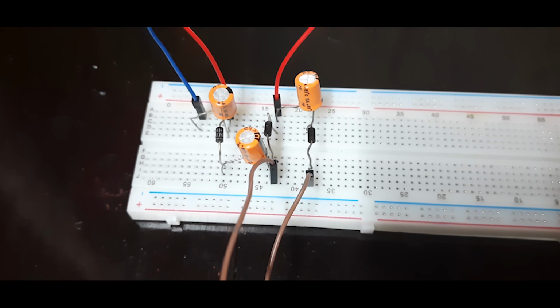Why you need to do this is that the capacitor would already be charged to a VP value. Say the VP value in our case was around 8. Now, if you reduce the input voltage to say 3, this VP will still be stored here and that will create an error in the output.